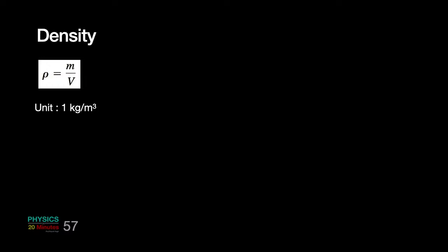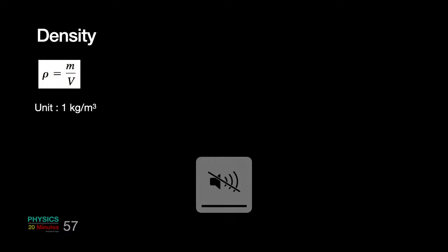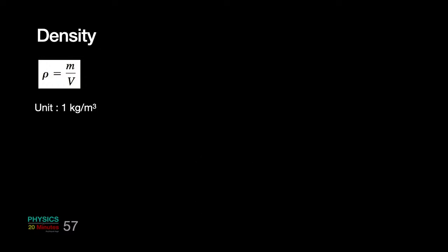In the case of fluids, the density may remain constant or may even vary. Depending upon whether the density is constant or varying, the fluid would be classified as a compressible or incompressible fluid. In a compressible fluid, the density can change because the fluid can be compressed, and more mass can be accommodated into a smaller volume. For an incompressible fluid, density remains constant.